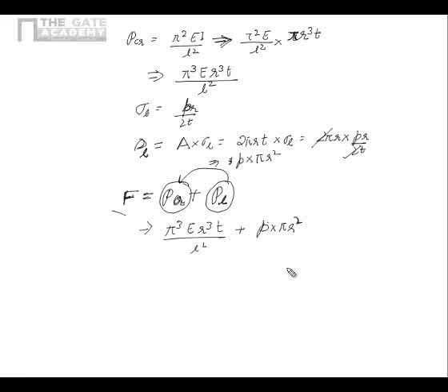Now let's invert this problem into a very interesting kind of problem. Let's say I have the same kind of thing, but the pressure is minus P, which means that there is a negative pressure acting in the pressure vessel, and the rest of the things are all same, E, R, T, everything is same. Now I ask a question, what is the negative pressure required to buckle the structure? Negative pressure means everything from outside will be coming like that. The pressure will be acting like this instead of outside.